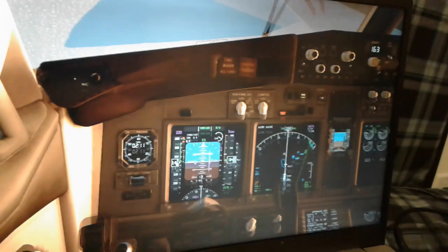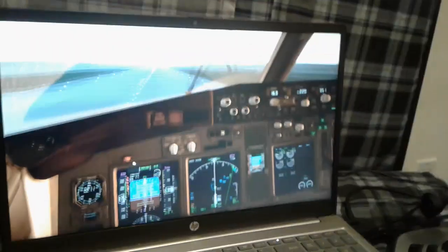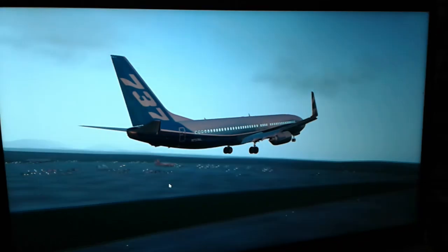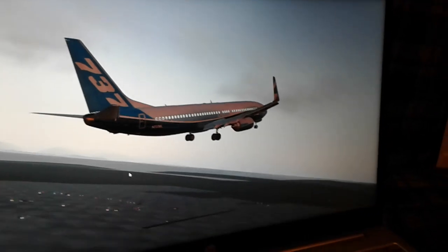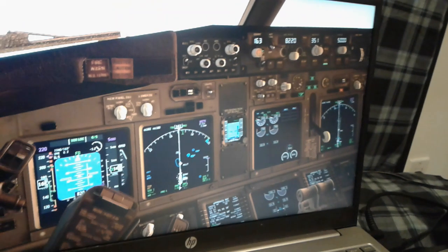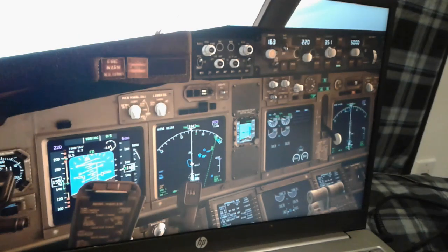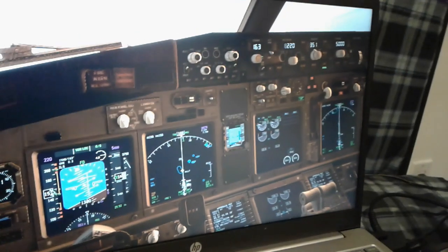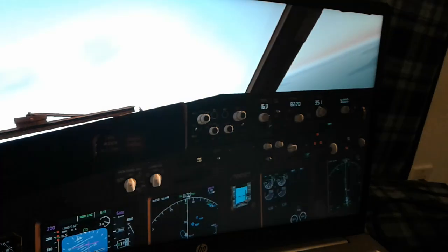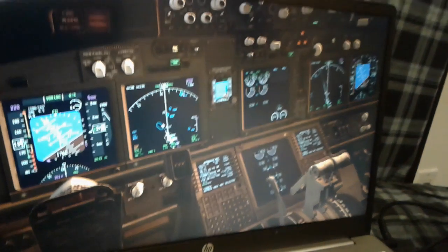So we use full takeoff power. Up it slightly, 5 degrees for this airplane, so it won't strike the tail for takeoff. And we start turning. 1000. Another gear up also. Less thrust. Speed brakes are retracted.